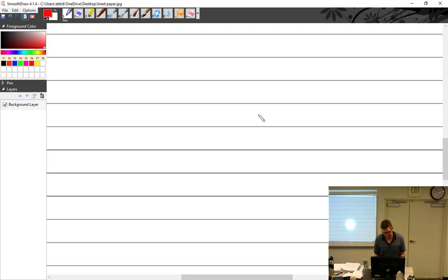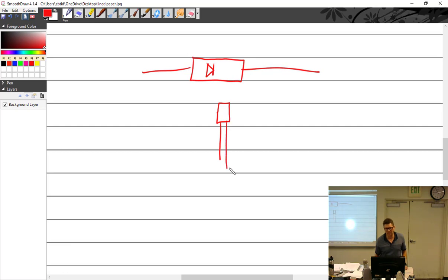How are they marked? So, if it's a diode that looks like this, with a wire sticking out each end, you're going to hope that somewhere on there you can see a marking that shows the direction. Well, if it's all faded out and missing, good luck on that one. Just change it out. But if it's an LED, one leg is longer than the other, and the longer leg is positive.